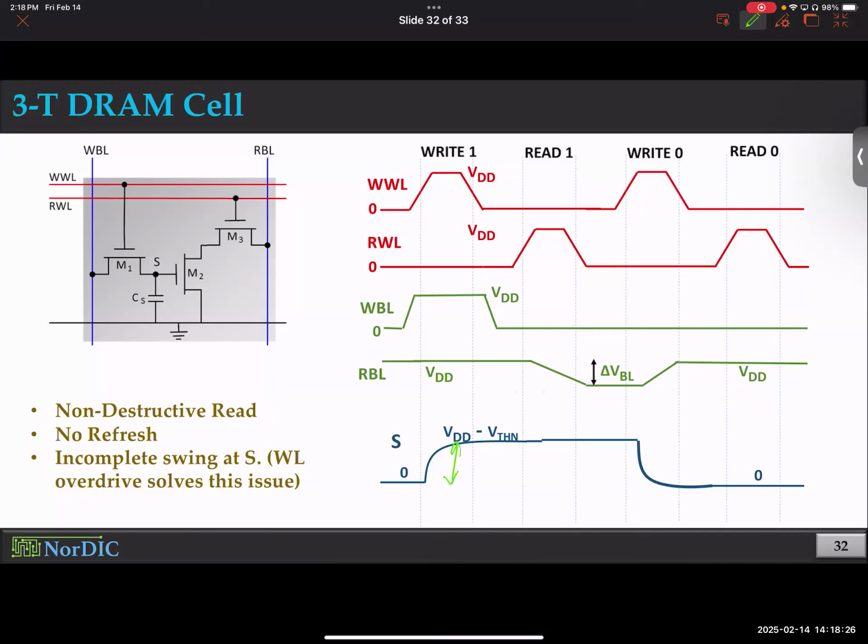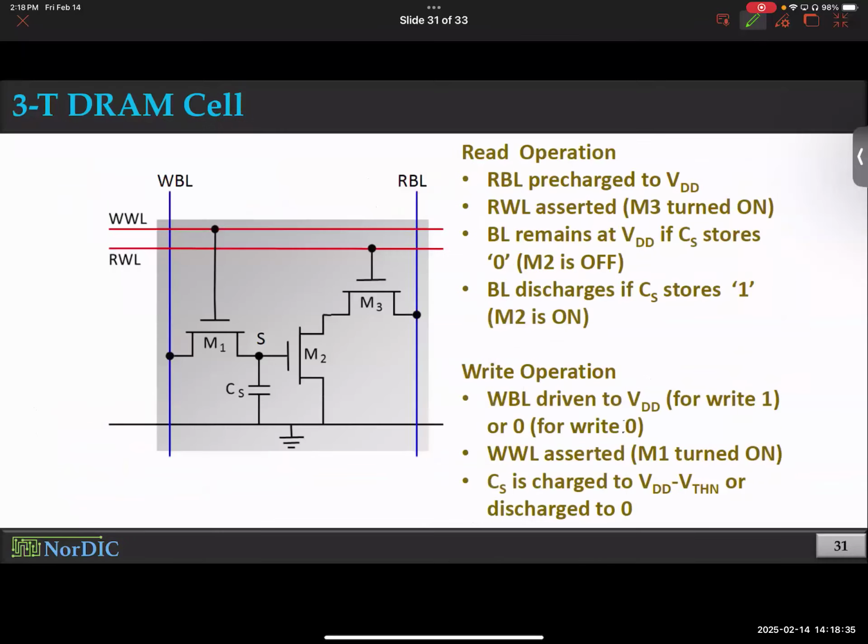And the refresh, right? Remember, the fundamental and major source of degradation of the storage node was reading. So let me give you some numbers. Imagine when you read, you change your voltage from 1 volt to 0.8 volt. A lot. But through leakage, to get from 1 volt to 0.99 volt, it might take 1000x more time. So it is a much more benign process. So yes, we do worry about leakage, but not that much.